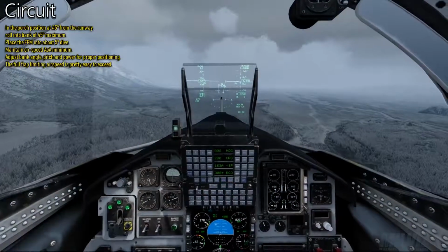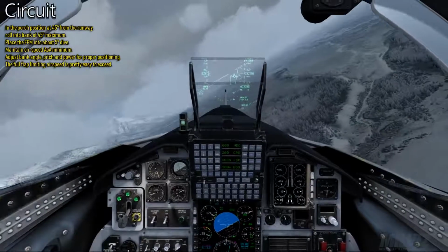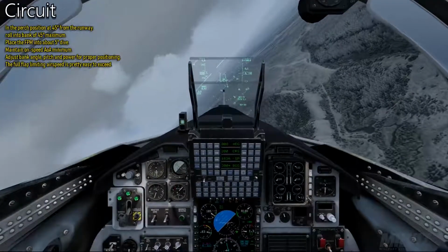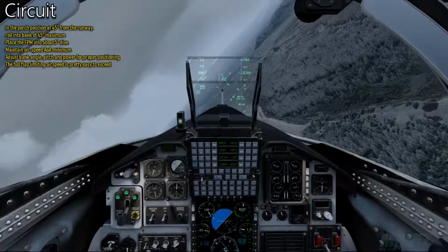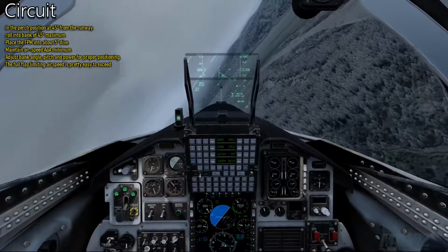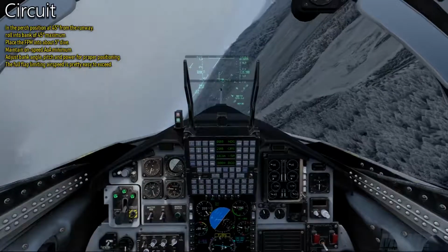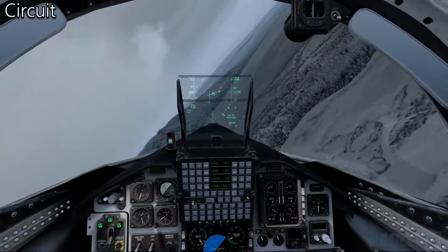In the perch position at 45 degrees from the runway, roll into a bank of around 45 degrees. Place the flight path marker into about a 5-degree dive. Maintain on-speed AOA minimum. Adjust bank angle, pitch, and power for proper positioning. It's very easy to exceed full flap limiting, so be aware of your airspeed.